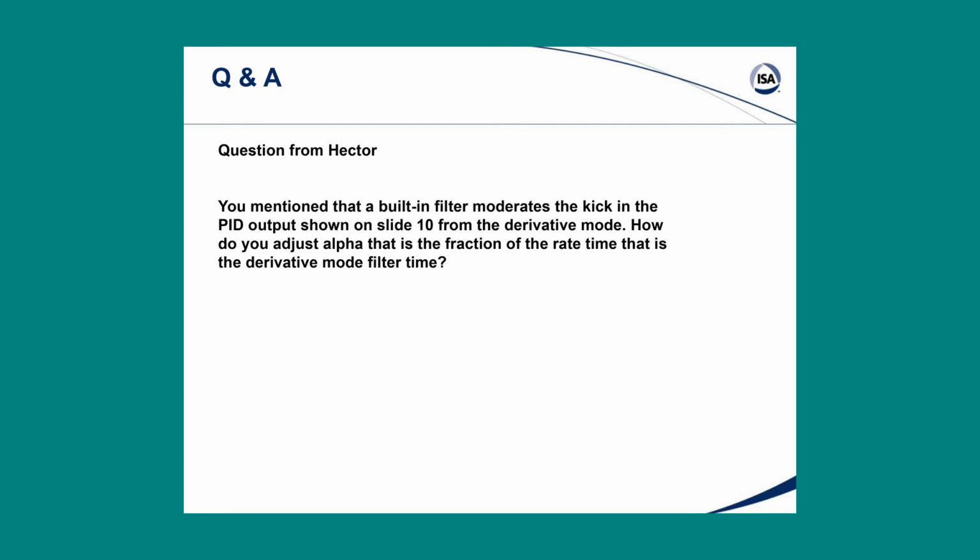And if you're doing a lot of set point changes, it can wear out the valve, but maybe more importantly, it could upset another loop. Say on the same header you're manipulating a utility flow and there's other people using those utilities, and so you make a sudden burst in that utility flow, it could affect other control loops. But normally we don't.